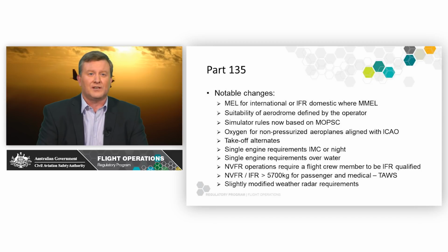We've changed slightly the requirements for single engine requirements over water. We have a new requirement for night VFR operations to require a flight crew member to be IFR qualified in accordance with Part 61. We have a requirement for night VFR and IFR operations for aircraft greater than 5,700 kilos only, for only passenger transport and medical transport, to have particular types of terrain awareness and warning systems fitted. And there's some slightly modified weather radar requirements, but they're very much largely identical to the current requirements for that.